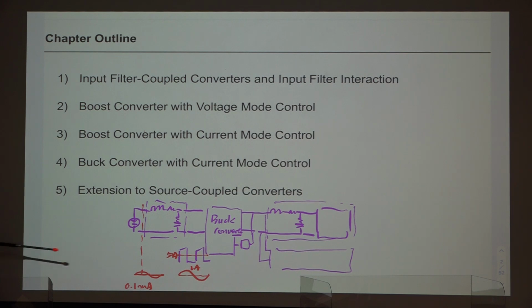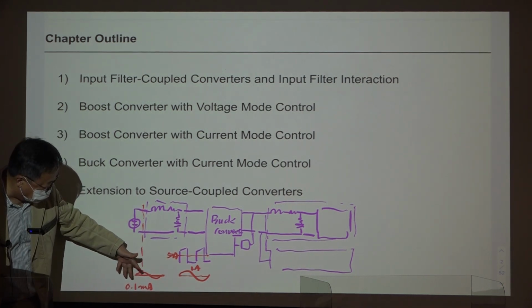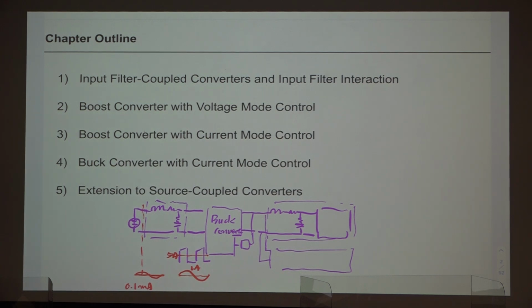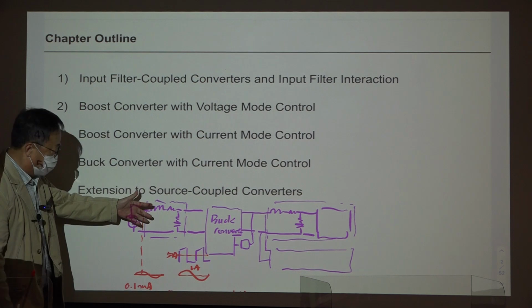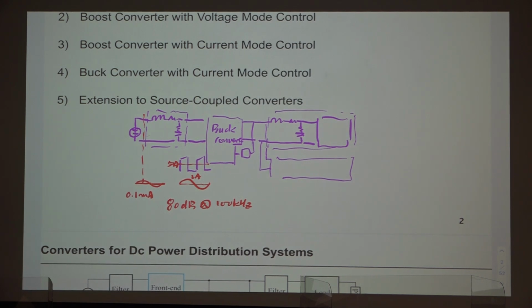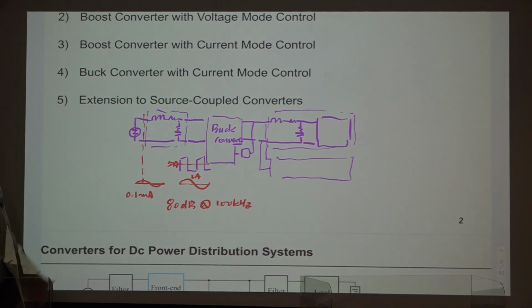So this 1 amp is going in, and that should be attenuated by this much, which is 10 to the minus 4, right? So it requires 80 dB attenuation at, for example, this frequency. So this is a huge requirement. Designing of this is not easy because the attenuation requirement is so large. So this is the requirement. You should obey this. They enforce this by law, so all the industry people should satisfy this.